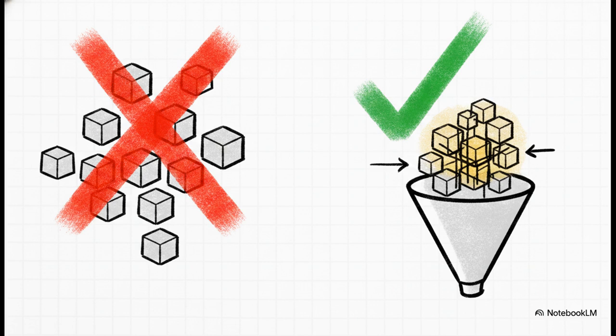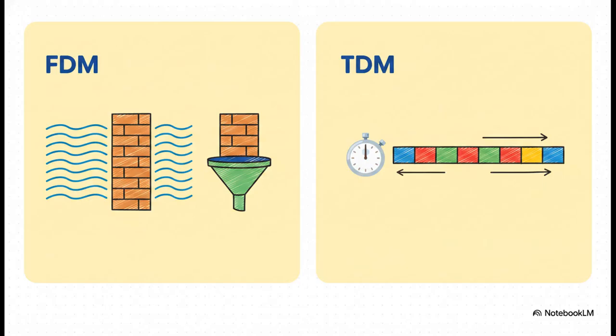The math on this is absolute. I love this comparison because it perfectly illustrates the core difference in how we stop signal collisions in the analog versus digital worlds. On the FDM side, we rely on frequency guard bands, represented by G. To get the total FDM bandwidth, it's the number of channels times the bandwidth of each, plus the guard bands in between. And FDM uses bandpass filters to separate everything out. But then, look at TDM. It doesn't use guard bands at all. Instead, it relies on strict timing synchronization and low-pass filters to stop aliasing. Do not mix these two up on test day. Guard bands are always FDM, synchronization bits are always TDM.